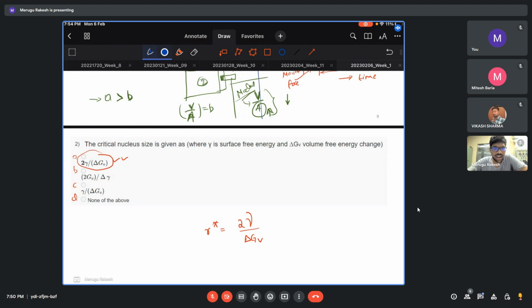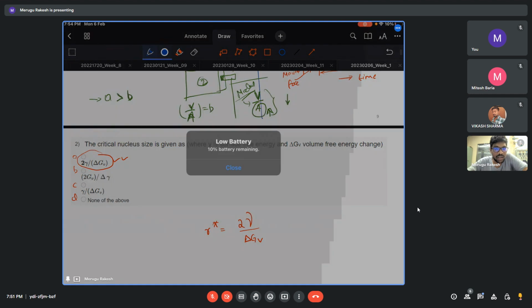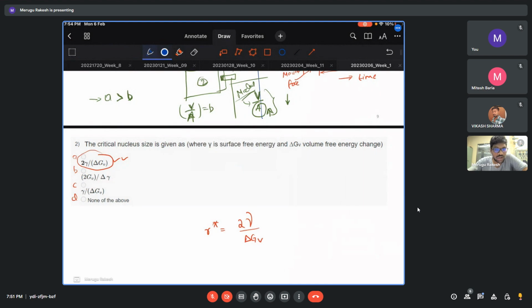I am seeing the phase diagram for this, whoever asked this question. If you go to the phase diagram of brass, there are so many phases in it. It actually depends on what concentration percentage of zinc you are taking, and we have so many phases such as alpha, beta, gamma, delta, and accordingly you have to select. Because we have different phases, the behavior may not be the same. Whatever I explained is for the very ideal case.